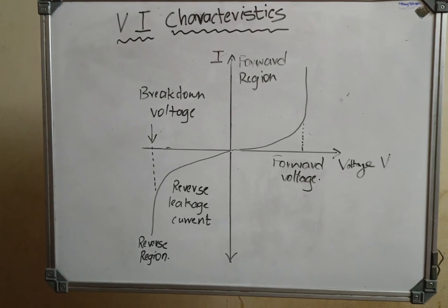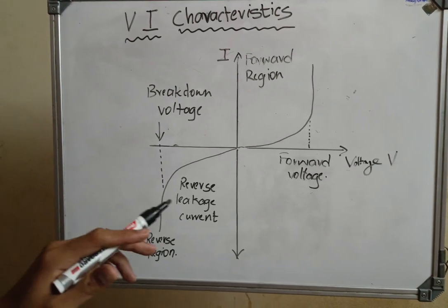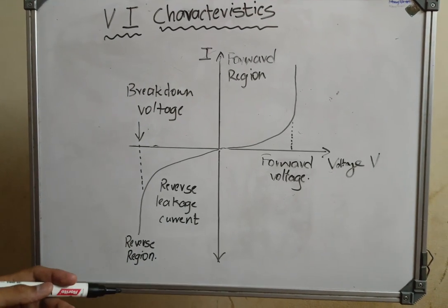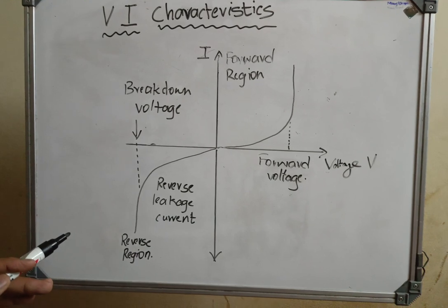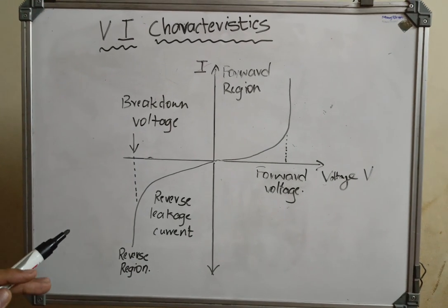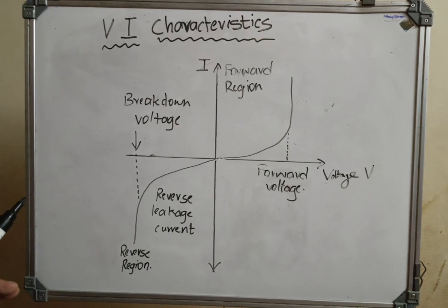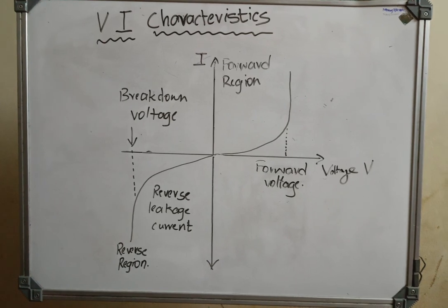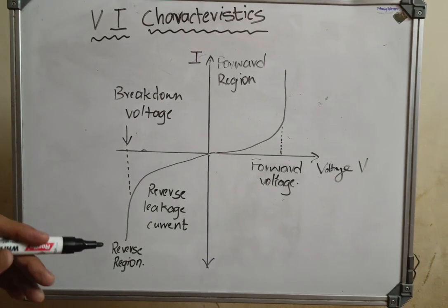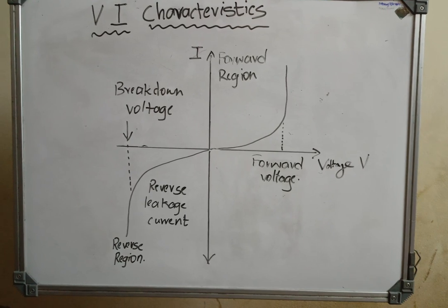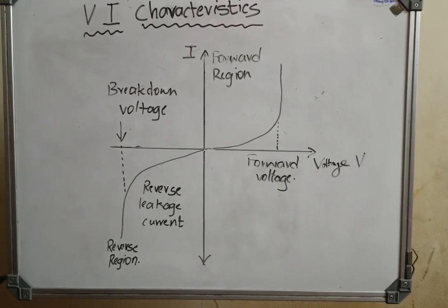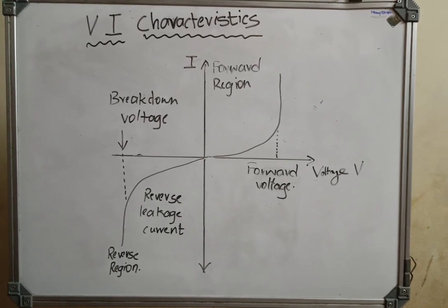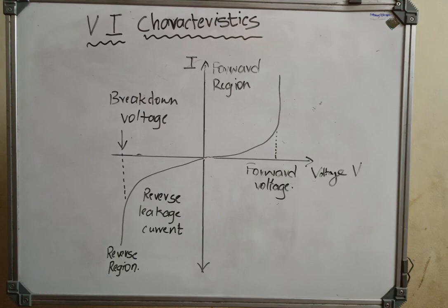When the p-n junction diode is in reverse bias condition, the P-type is connected to the negative terminal while the N-type is connected to the positive terminal of the external voltage. This results in an increase in the potential barrier. Reverse saturation current flows in the beginning as minority carriers are present in the junction. When the applied voltage increases, the minority charges will have increased kinetic energy, which affects the majority charges. This is the stage when the diode breaks down. This may also destroy the diode.